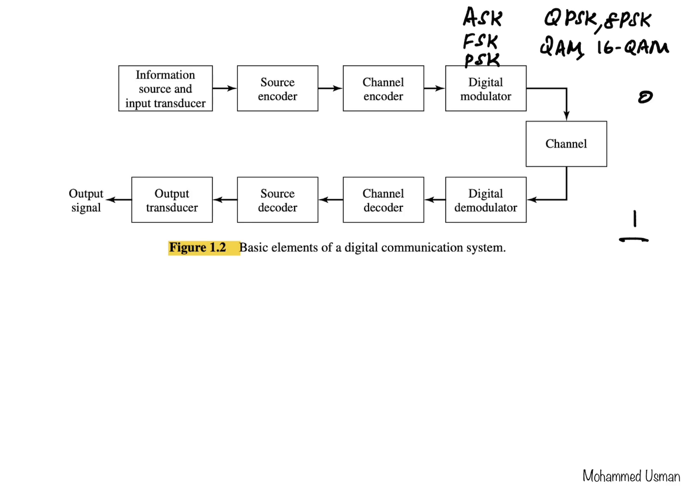Basically, the idea is that with the transmission of a single symbol, we want to send through as many bits as possible. So with QAM and 16QAM and 32QAM and so on, we are trying to send more bits within the same symbol, and we use various techniques to achieve that. Okay, so that's the job of the digital modulator.